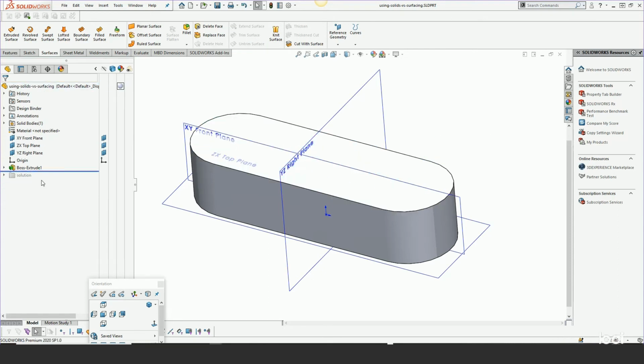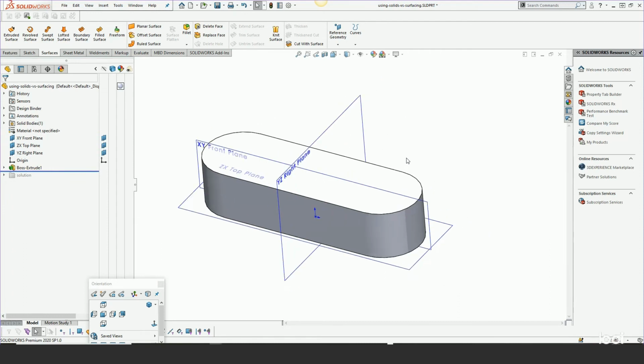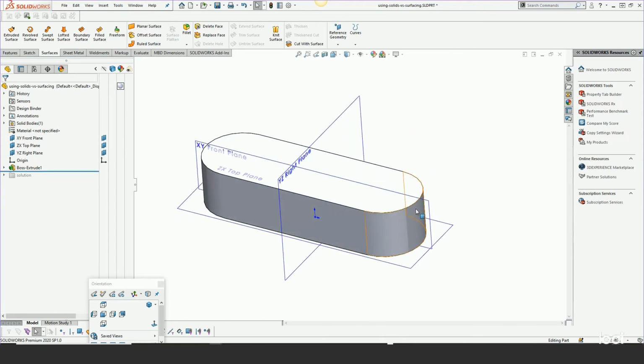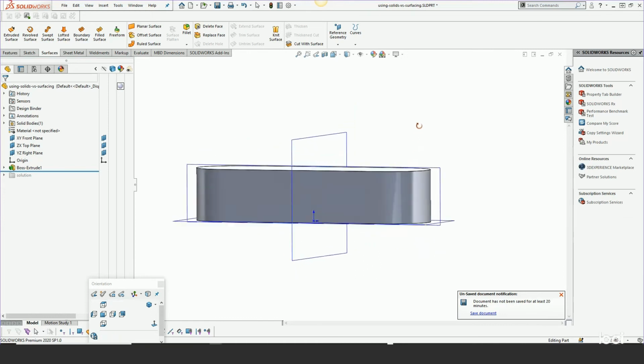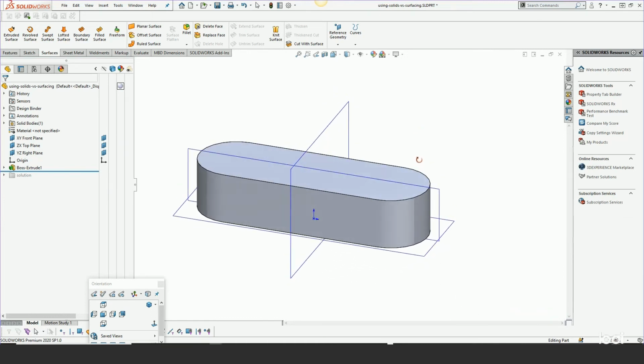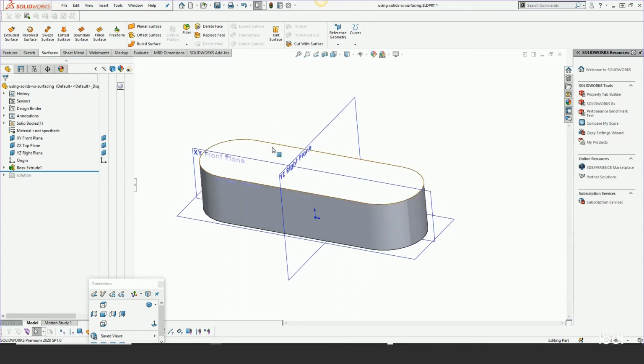So it's logical for this model to extrude a profile and extrude it with draft, if it's a molded part, which it probably will be. But from this point on, how do you get that dome in a very robust and simple way? Now, you might want to use the dome feature, but unfortunately for shapes like this, dome doesn't work that well. Let's try that.